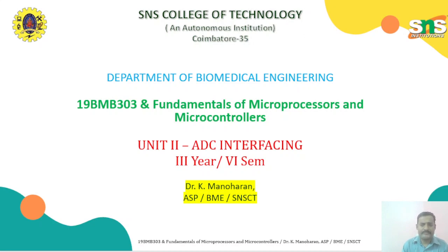So today in class we are going to discuss the ADC interface. ADC is analog to digital conversion. The real world signals are analog in nature, so we cannot directly interface this analog signal to the microprocessor. That's why we need to convert analog to digital, and for that we use analog to digital converters.